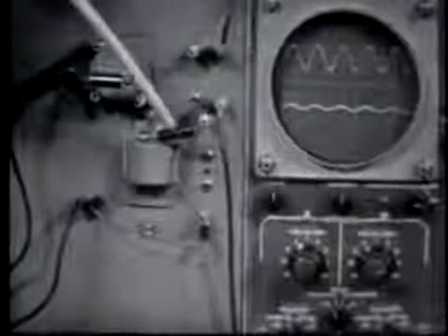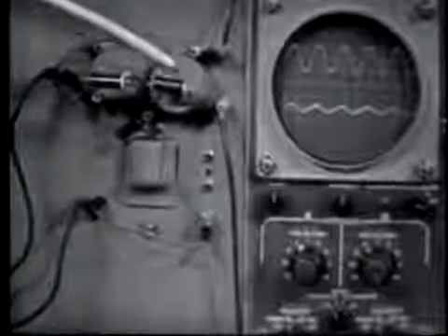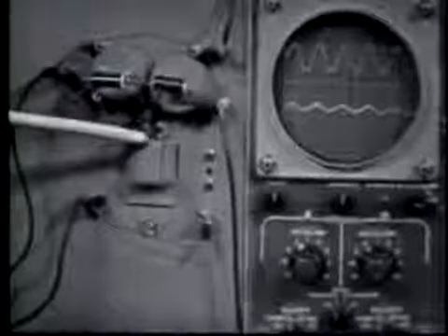Now to make the T section, we'll need another parallel tank in the output leg of the series position, and we'll need to move our series tank over to the junction between the 2 parallel tanks. Now let's do this. Okay, parallel tank here in the input series leg of the filter and a parallel tank in the output series leg of the filter. And our series tank now is connected from the junction of these 2 tanks down through the capacitor, the inductor in series, and down to ground. So we have a T section band reject filter.